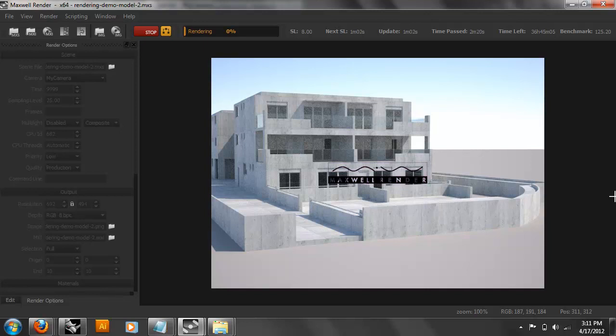The noisiest parts of the image are going to be your glass, because that's catching reflections from the rest. It has to render the other bits of the image so that the glass can render what's reflected. Does that make sense? Crazy, right? If you have a lot of glass, you need a lot of sample levels, and it's going to take longer. These giant glass buildings are painful on the computer. I don't want you to change your design, but I'm just telling you.